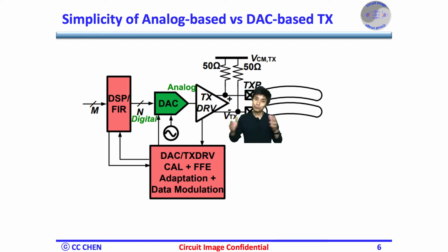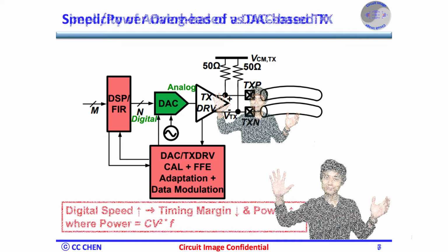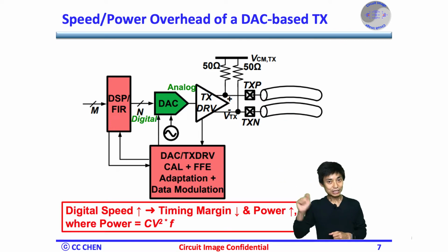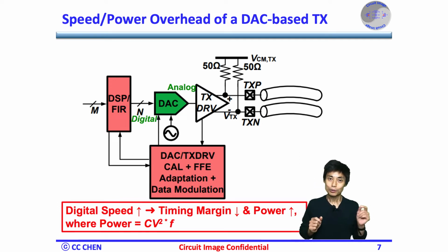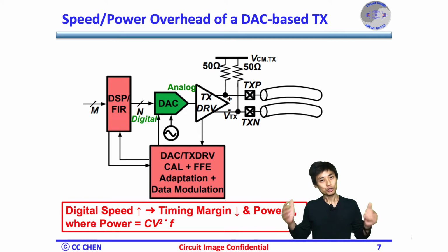If that's the case, why don't we apply the DAC-based TX? Think about the digital limitation for 5 seconds. Bingo! Digital gates can do much complex digital processing, which means the digital circuit is too complicated to operate at high speed due to the digital timing constraint. In addition, very complicated digital gates operating at a high rate consume more power, even though the speed constraint can be mitigated through a parallel processing technique. The total power would be similar and huge.